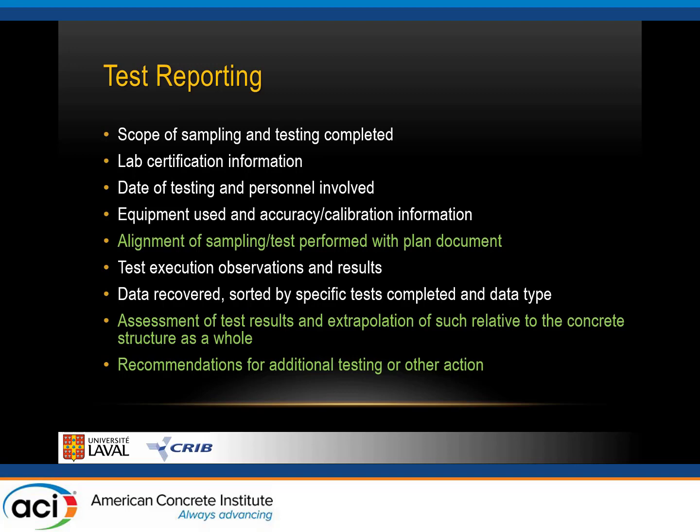Yes, sometimes they use, for example, steel beams for repairing some deflection in the slabs. So my worry is whether there will be any incompatibility of the materials in the deformation, because steel has different behavior than concrete. Now it depends on the way the connection is made between the steel and the concrete member. But this has to be taken into account in the design. Okay, thank you.